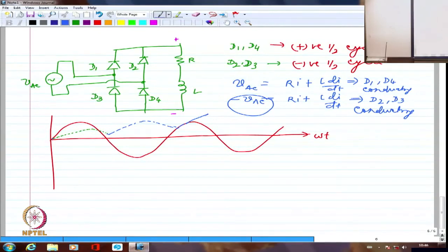There is no steady state otherwise, like DC. You're not going to have a steady value here. No way. Rather, whatever initial point I get at the beginning of the half cycle, does it become a constant eventually? The maximum value and the minimum values, do they become constants eventually? Once they become constant, we call it that the steady state has been achieved. Please don't confuse it with DC, because you cannot see a steady DC here. No way. You would always see an oscillatory DC current.